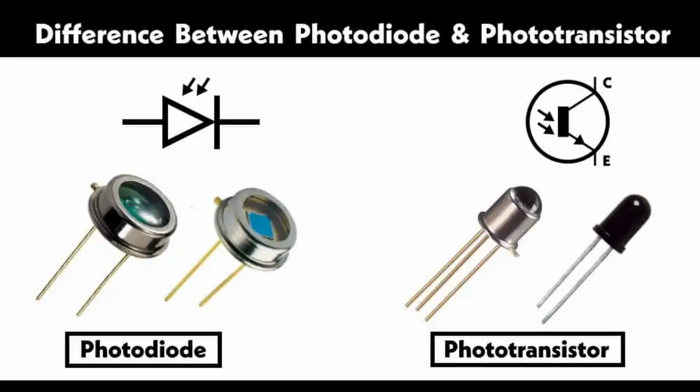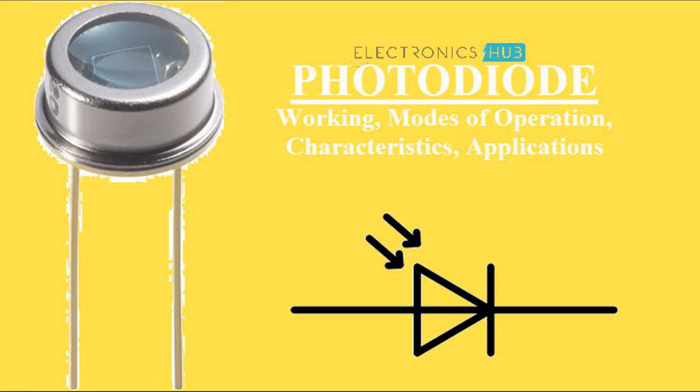9. Temperature sensitivity. Impact. Photodiodes are sensitive to temperature variations. As temperature increases, dark current and noise increase, which can affect the overall performance. Compensation. In some applications, cooling or temperature compensation circuits are used to stabilize performance in varying temperature conditions.